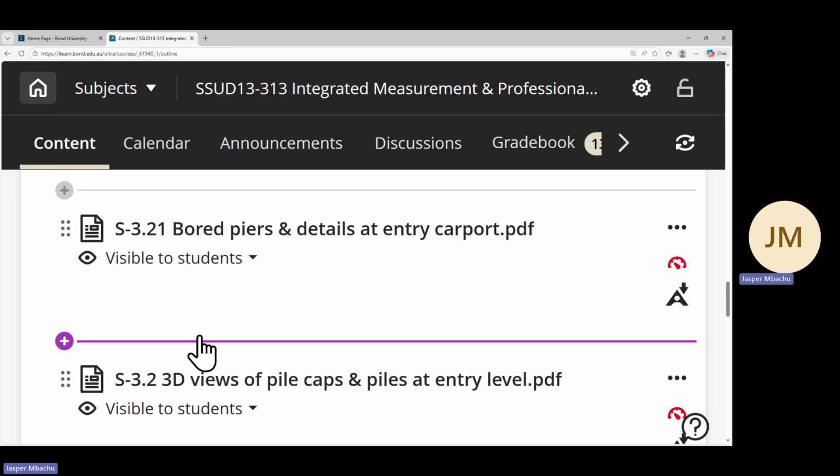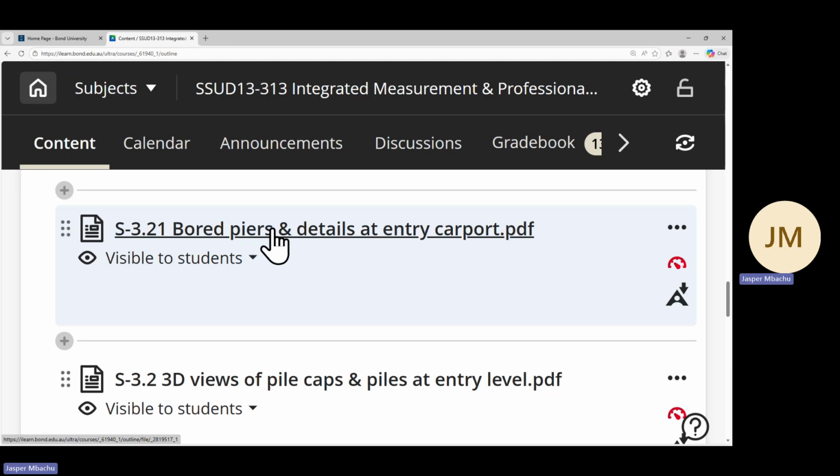that you have gained high proficiency in digital takeoff. You do not do digital takeoff and provide quantities and think you've done your job, but you must provide trails of the documentations that justify what you're doing. So somebody might ask you, where did these figures come from? So that is what ISO 9001 demands, that you provide trails of what you're doing for somebody else to have a look. And the person may not have the knowledge of Revit, but the 2D documentation.